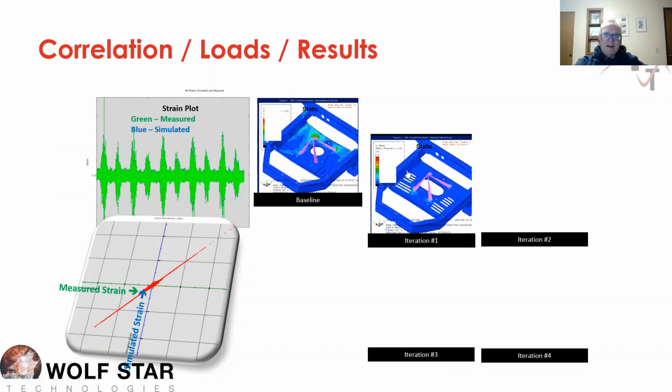You can see they got some high stress concentrations up here. And I said, perfect, give me that FEA model. Let me run the loads in the FEA model, and let's see what's going on. I'm going to show you durability plots in the next slide. But then, working with the engineers, we came up with a different pattern here. So we came up with a new hole pattern on the system.